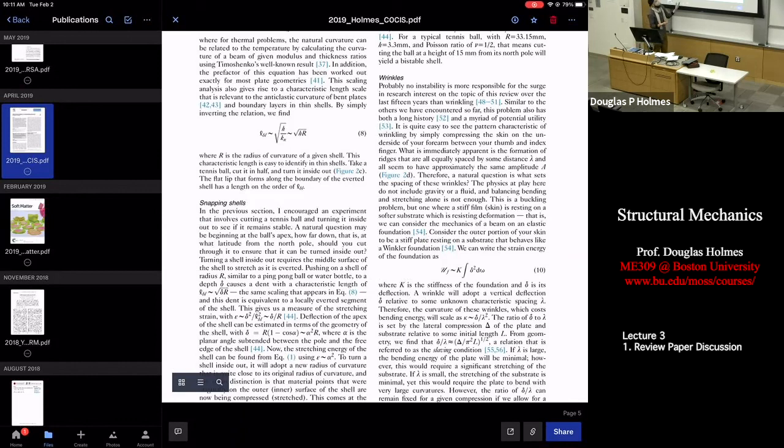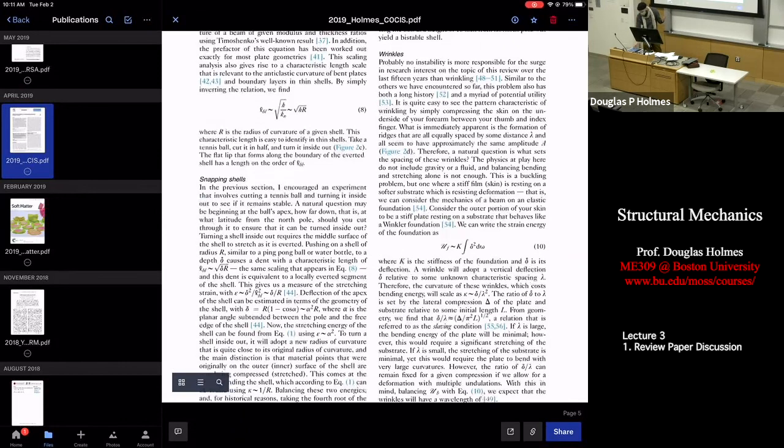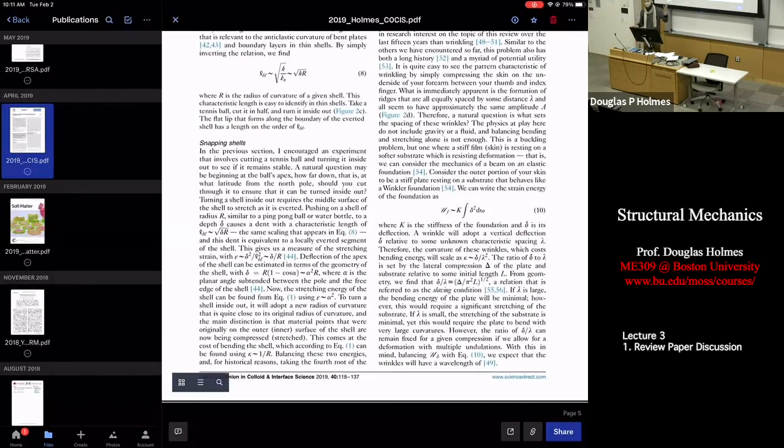This is a really simple model. It's just using the same bending energy that we've learned, right? And all it does is, this equation number 10 here should look familiar to you. It's sort of like the energy of a spring, like kx squared, but we replaced x with delta. And now we have this integral, which is probably a little bit like, all right, where'd that integral come from? kx squared is the energy stored in one spring.